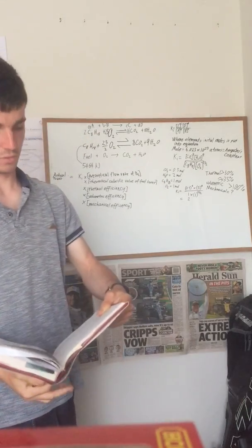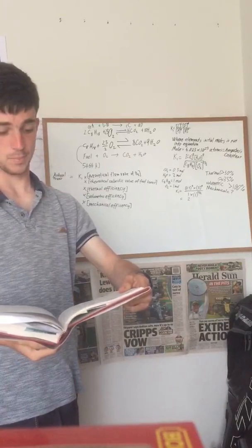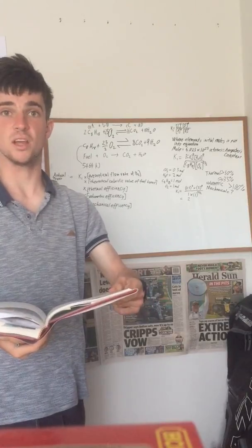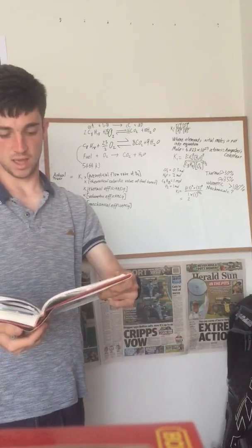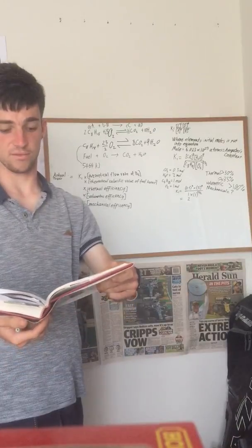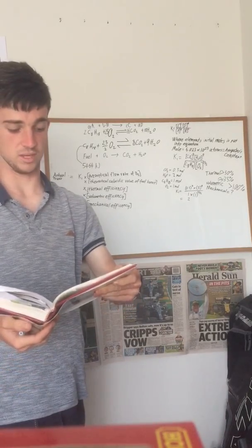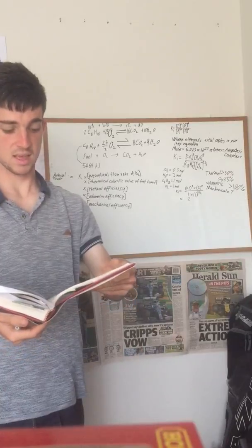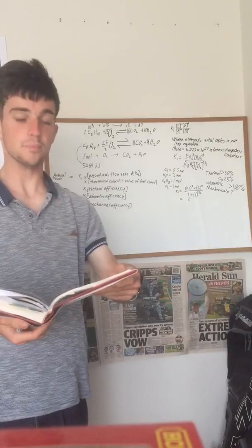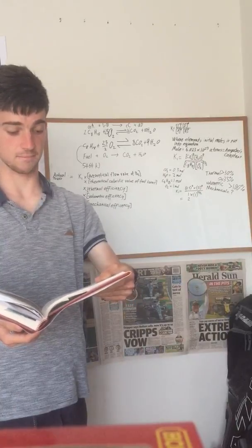It says right here in this book, in reality, the actual heat energy released by the combustion process depends on numerous factors, the most important of which are the compression ratio and the heat losses to the cooling system of the engine. The cooling system of the engine is necessary to prevent components from exceeding their natural limits, their material limits. These all add up to a loss of energy that is quantified as thermal efficiency, the ratio of actual heat released to the theoretical heat released.